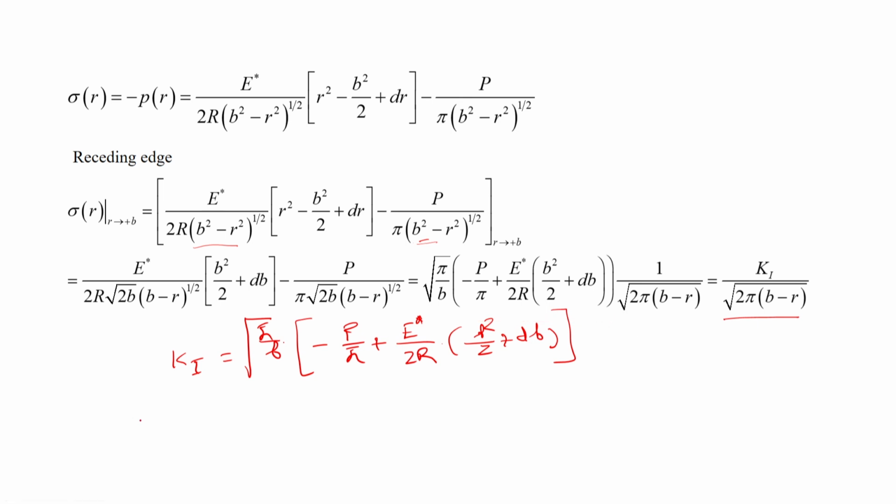And so the fracture energy, or the strain energy release rate, is equal to K1 square by 2 E star.